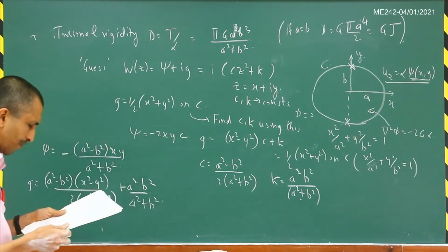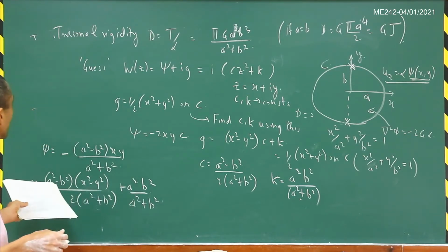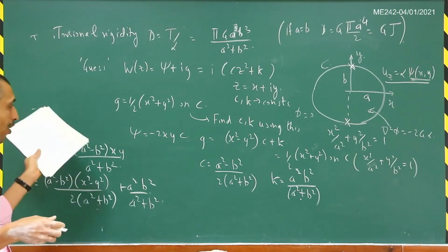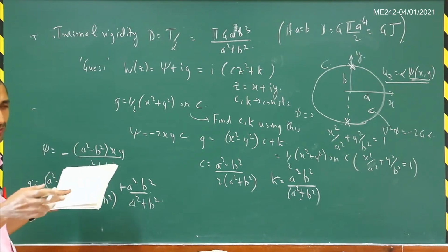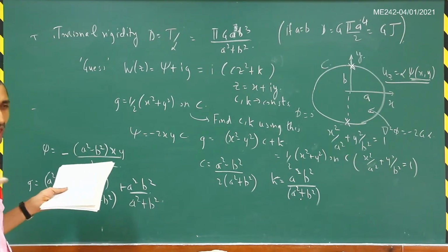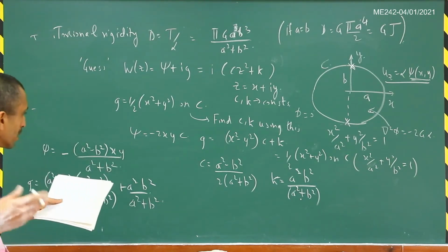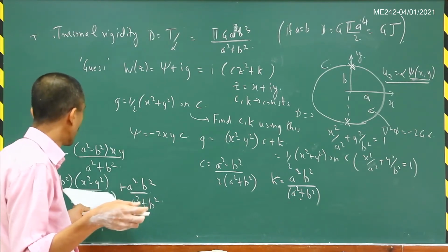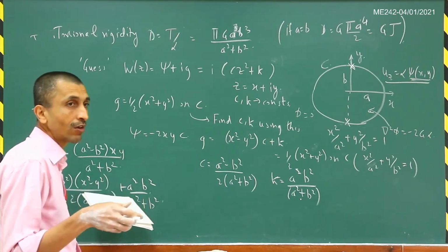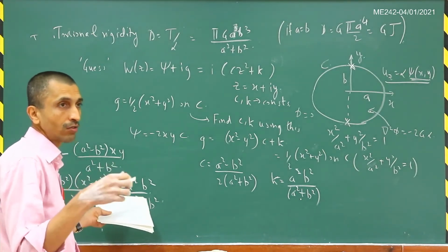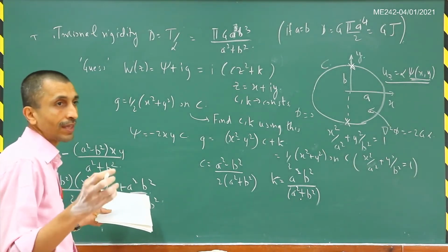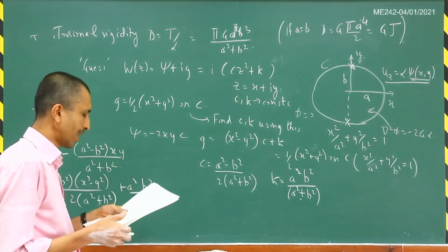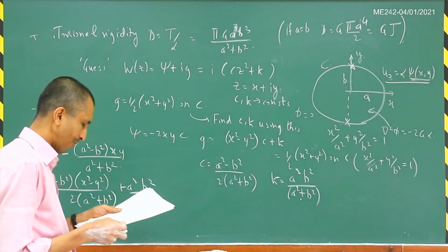So this is the expression that you get. Now, as I said, this g expression would also have been obtained from the phi expression, using half of x square plus y square plus phi divided by 2G alpha. We could have found g from phi and then used the Cauchy-Riemann equations to find psi. But whichever way, any of these approaches is fine here.